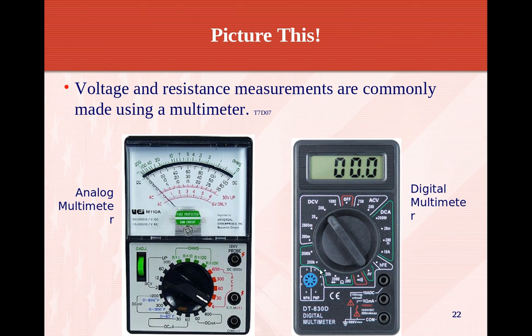This guy is resistance right here. You don't have to zero anything out, it automatically zeros. You just switch to the range. And there's also auto ranging meters too. This is a manual range meter where you have to select the range that you want. There's auto ranging meters out there that you just put in ohms and it automatically does the range for you. This one's one of the cheapo ones that you can probably get for around $5–6.